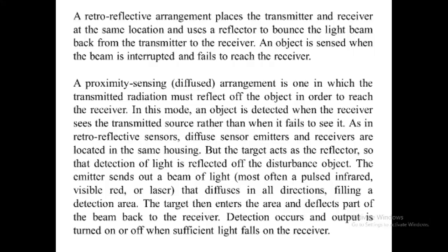Through beam sensors are also the best choice in a dirty environment. It's important to keep in mind that at least two separate parts need to be installed in order to make this device work correctly.